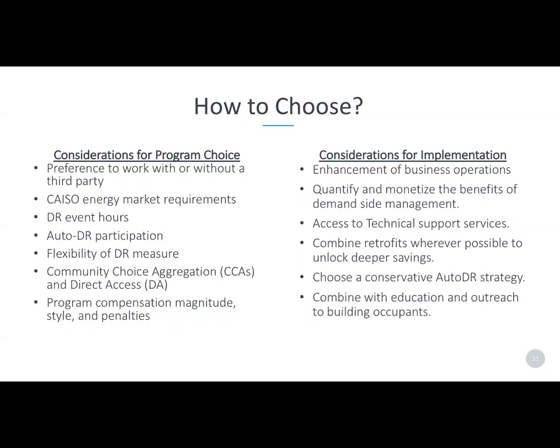For example, since the 2013 Building Energy Code, a lot of lighting retrofits would actually trigger a demand response requirement. So if you're doing a comprehensive lighting retrofit, that is the time to consider demand response participation, because the marginal cost of adding on DR controls is fairly minor once you're already doing an advanced lighting controls installation.